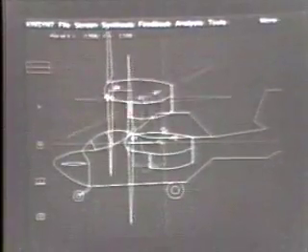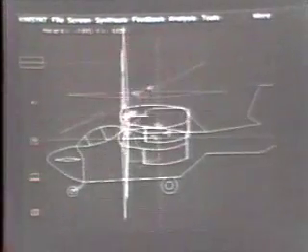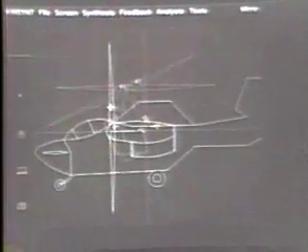Now the designer has returned to the synthesis part of the program and is specifying a 4th design position. Pulling the rotor assembly out and positioning it in its 4th position using the pen on the data tablet, the designer now is rotating the rotor into its 4th position. And the Burmester curves, the loci of possible fixed and moving pivots compatible with all 4 positions, are now being shown. These curves are being shown in red and green, the locus of fixed pivots in one color and the locus of moving pivots in the other color.